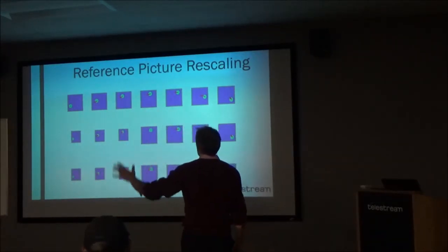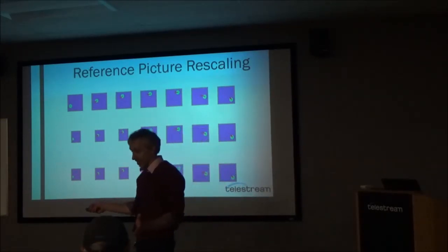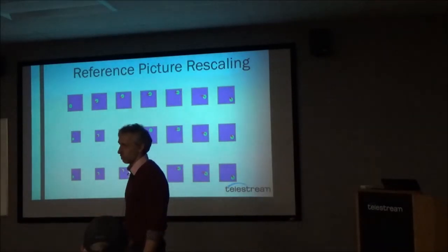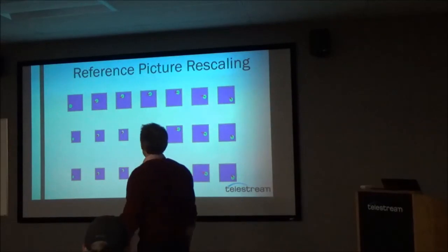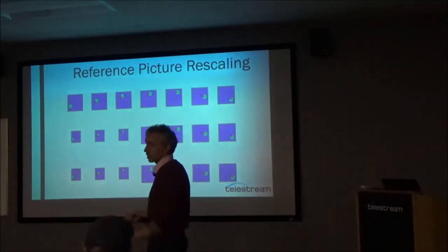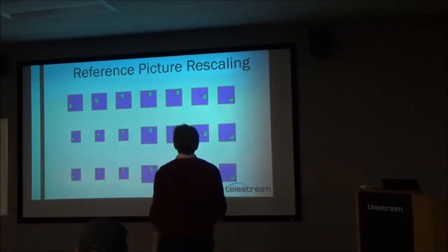I'm waving my hands here. I don't know how, but now you can do this. You can switch streams, and you can still have motion vectors that point to the picture that was from a different resolution. They're obviously adding this with a view to live streaming and switching resolutions and not having to transmit as many iframes as you would have to if you didn't do this.